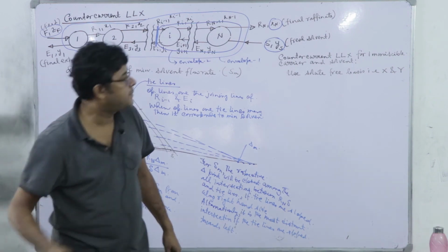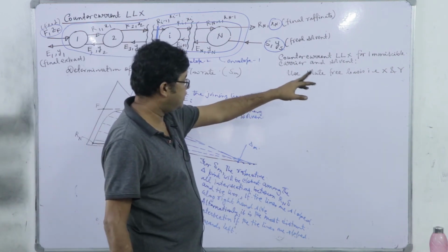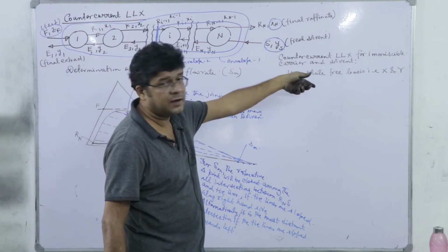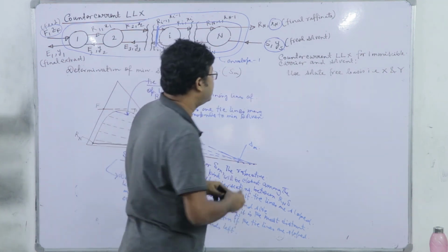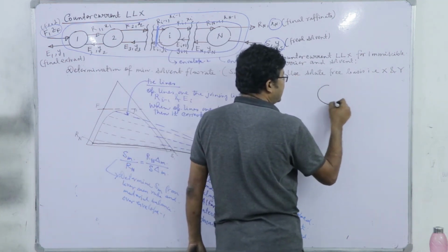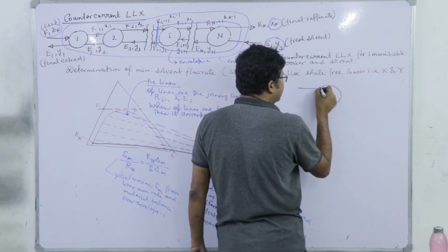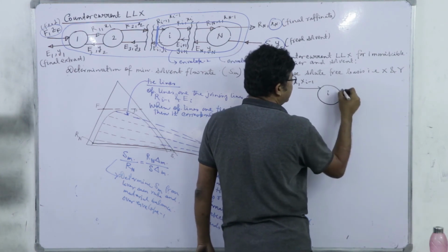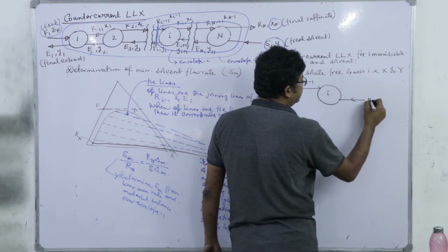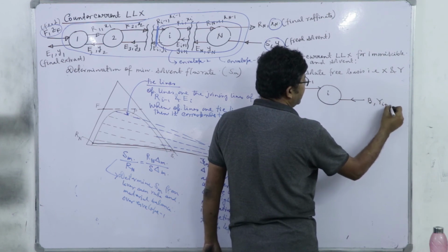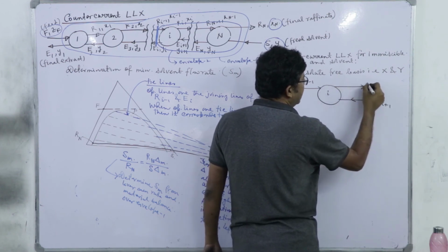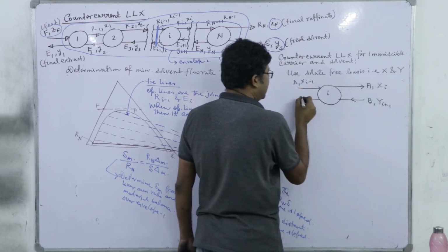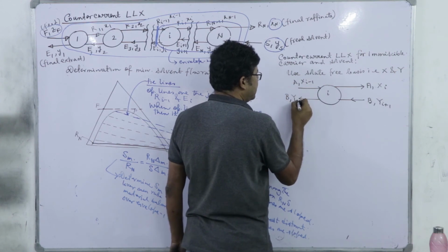It is the kg of C per kg of B, that is Y, and kg of C per kg of A, that is X. So, if I consider a general stage i, so here we have A and x i minus 1, and here it is B y i plus 1. Going out is A x i, and here it is B y i.